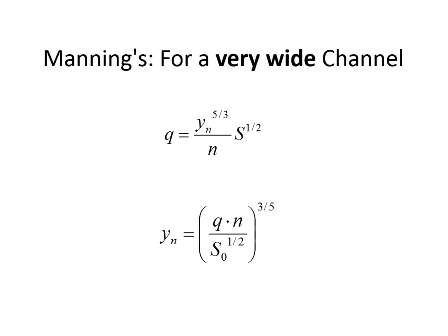For a very wide channel, we assume that it's rectangular, so that's why you can calculate a flow per unit width. You can't calculate a flow per unit width for a trapezoidal channel. That doesn't make any sense in the case of a trapezoid. Thank you, yeah, this is a trapezoid.